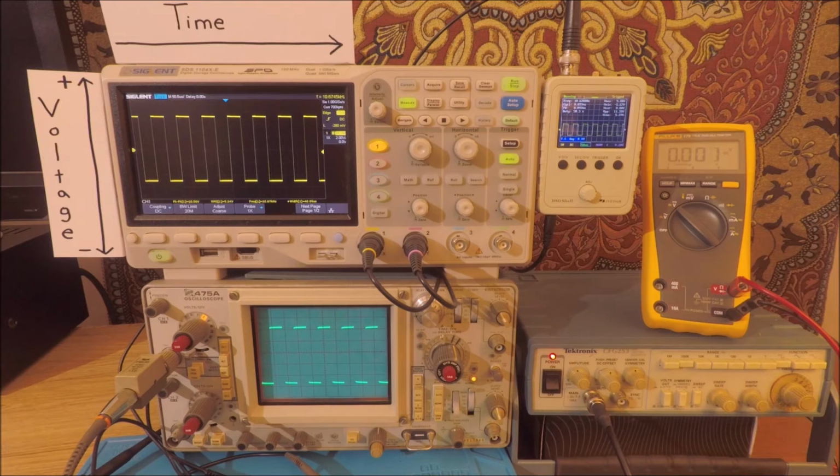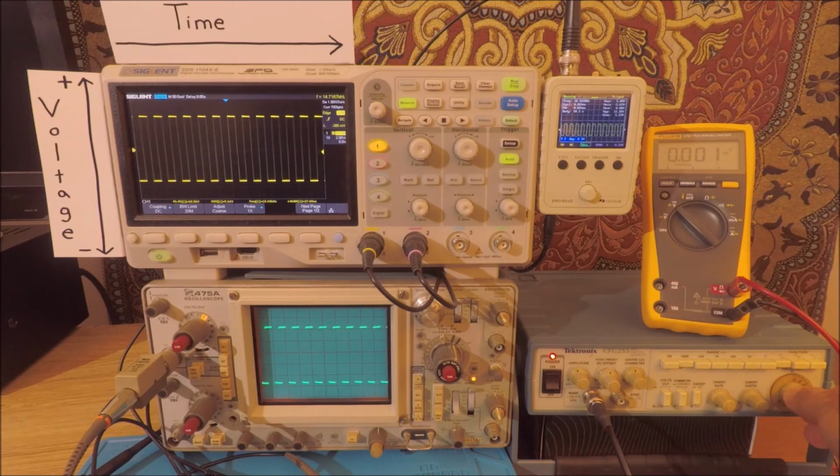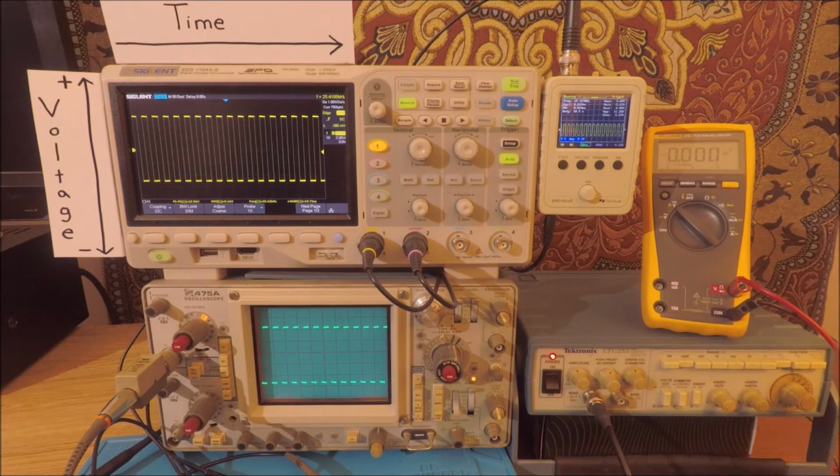What that means is that we have a very harmonically rich signal being displayed here on each of our oscilloscopes, although it's a very low frequency signal. It's 10 kilohertz. And we can see a nice representation of that. But we know each of these oscilloscopes is going to have a finite amount of bandwidth in order to display this waveform. And we can identify what that bandwidth is if we start to increase the frequency of the test signal. So here we're up at 20 kilohertz. We've doubled the frequency. All looks very nice still.